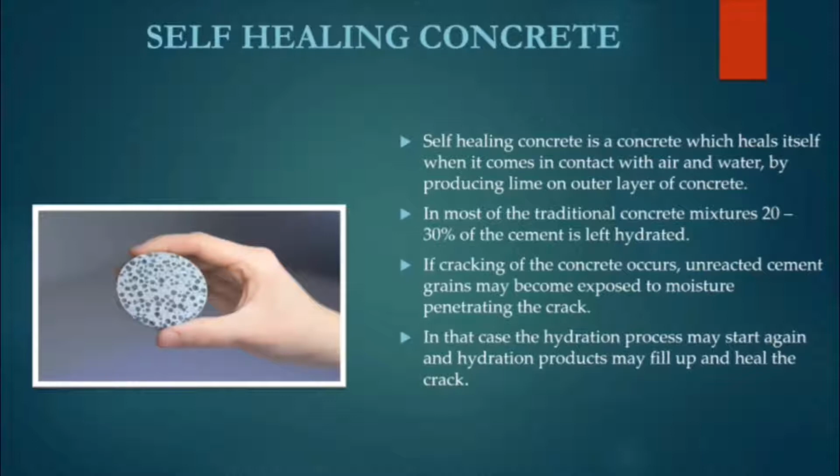In most traditional concrete mixtures, 20 to 30 percent of the cement is left unhydrated. If cracking of the concrete occurs, unreacted cement grains may become exposed to moisture penetrating the crack. In that case, the hydration process may start again and hydration products may fill up and heal the crack.